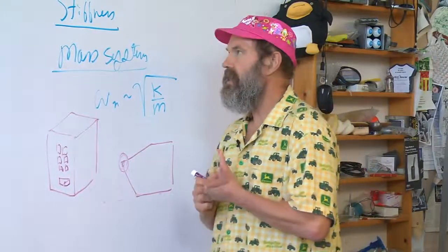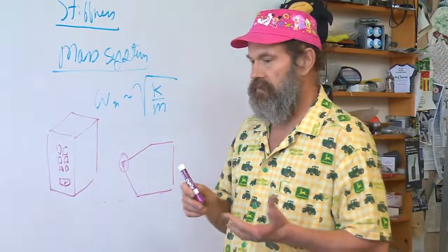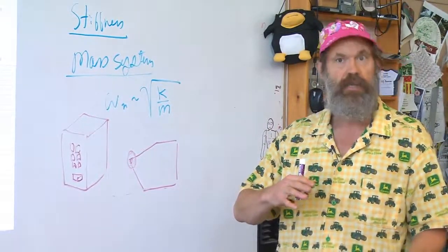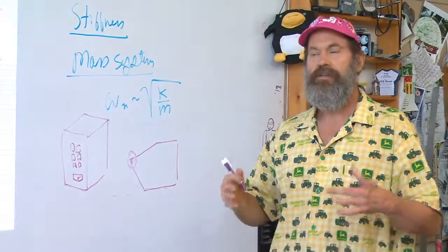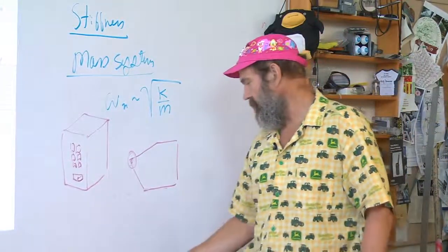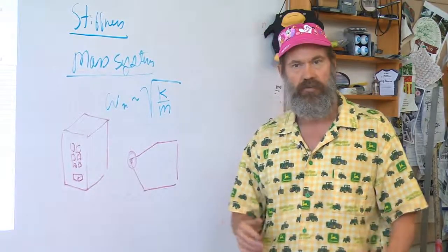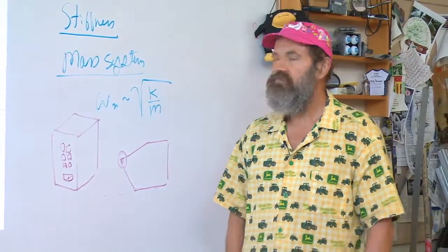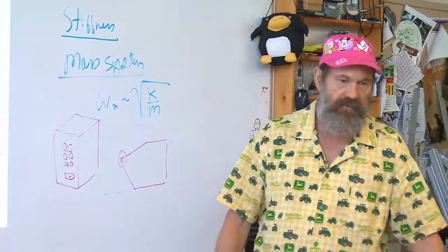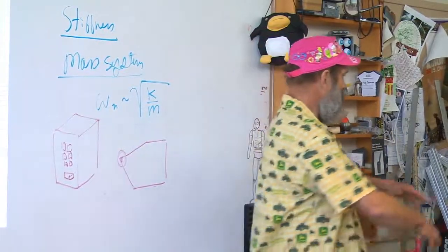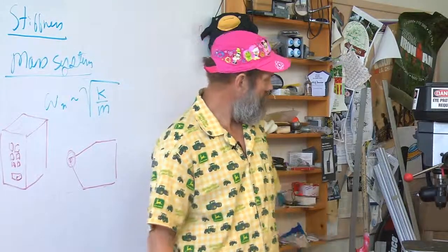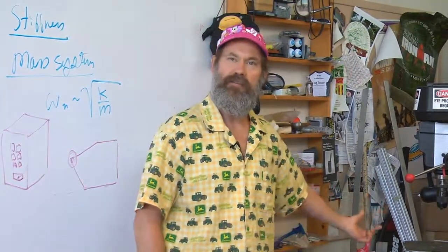So even though you may not intend to have your structure used in a way that could have an instability issue, you have to assume that it will be misused. How would you attack it? One of the really good ways to do this kind of evaluation on your machine is to go find some kids, maybe some teenagers somewhere, in the summertime, they're bored, they've got nothing else to do. Build a plywood mock-up, something that's safe. Say, okay guys, you're bored, what would you do with this thing? How could you hurt it?